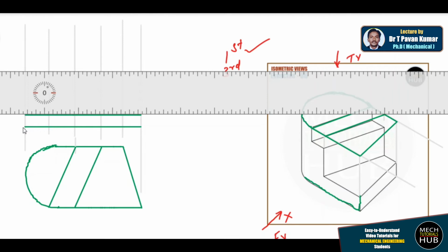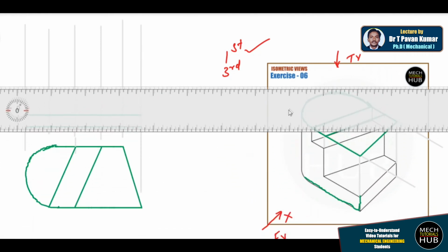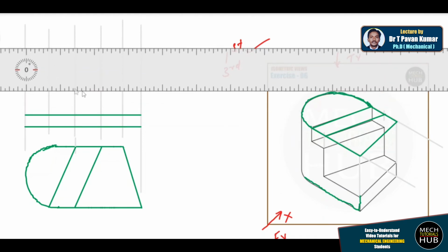This is also fine, and we need to know the overall height. Okay, let us consider from the bottom, let us mark it as some 50 mm. If this is 10 mm, this is going to be that 50 up to 10. Okay, now here I have just drawn a horizontal. That horizontal is nothing but this horizontal. Now this curve looks like a straight line only from the front. Remember, I am drawing this view observing the component from the front. Okay, I have drawn this view by looking at the component from the top.